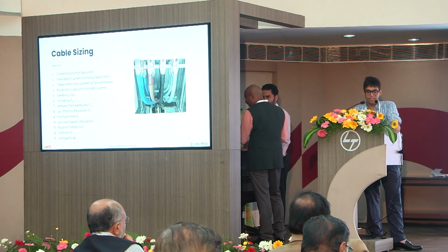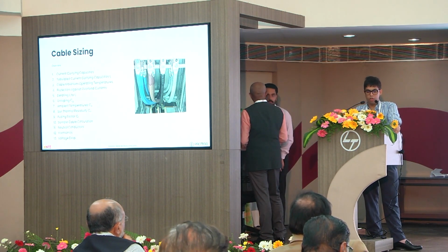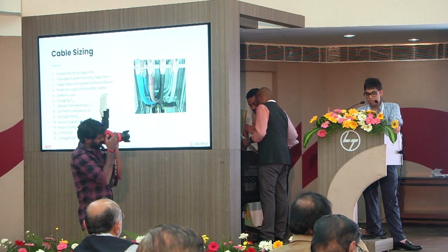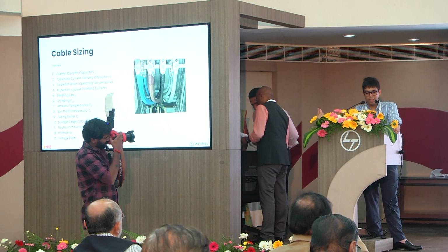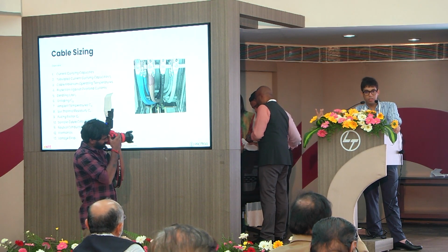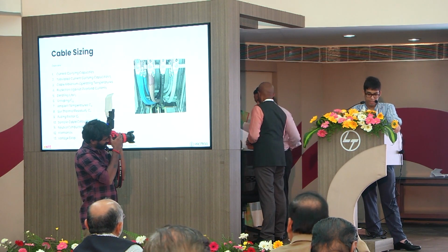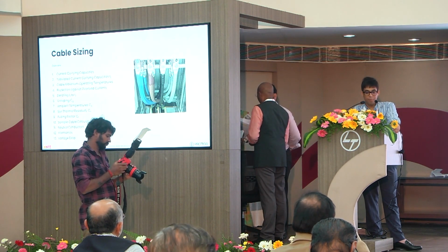These factors are basically, IS 732 looks at grouping, and even NEC, the ambient temperature, soil thermal resistivity, and there is a ninth one called fusing. The fusing as a factor is not mentioned in 732, but reference is made. We'll get to that. We will do a sample cable calculation.